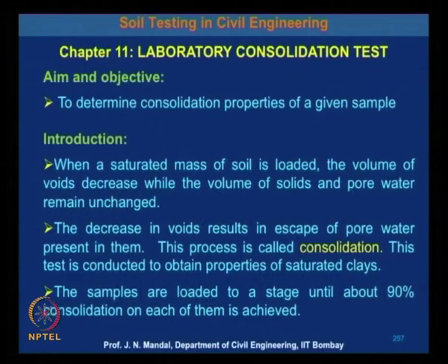So, when a saturated mass of soil is loaded, the volume of the void decreases while the volume of the solids and pore water remain unchanged. The decrease in the voids results in escape of pore water present in them.